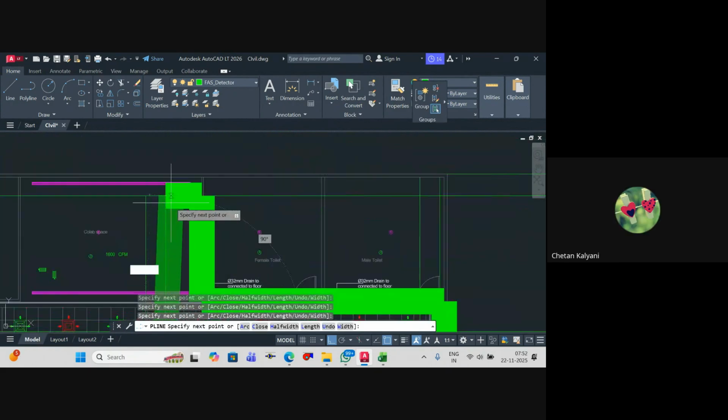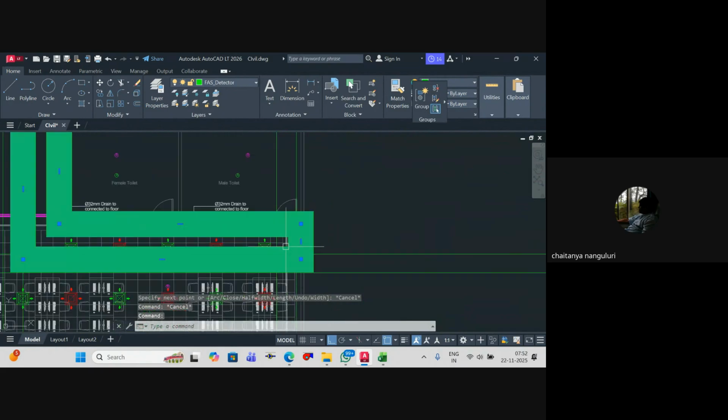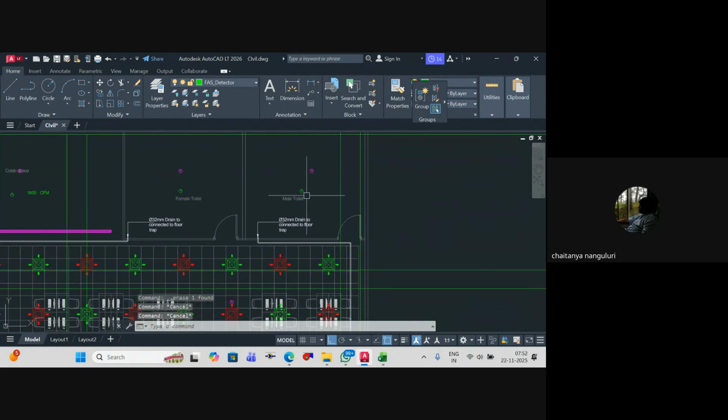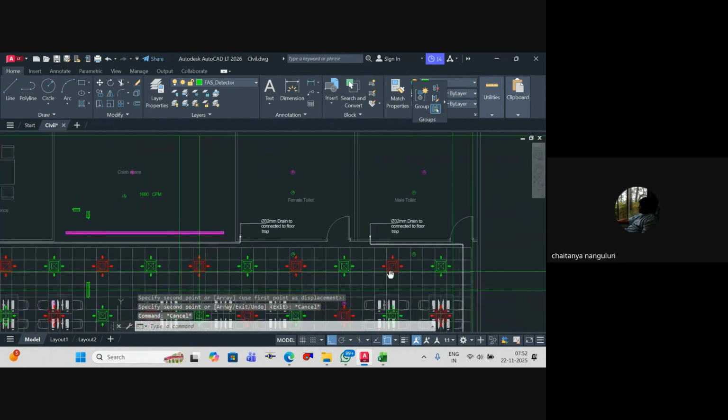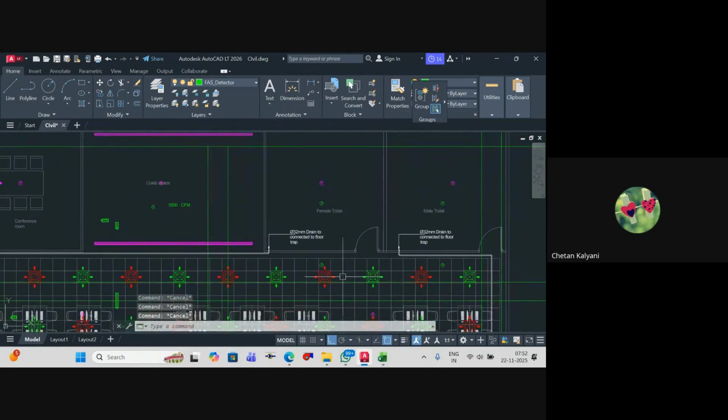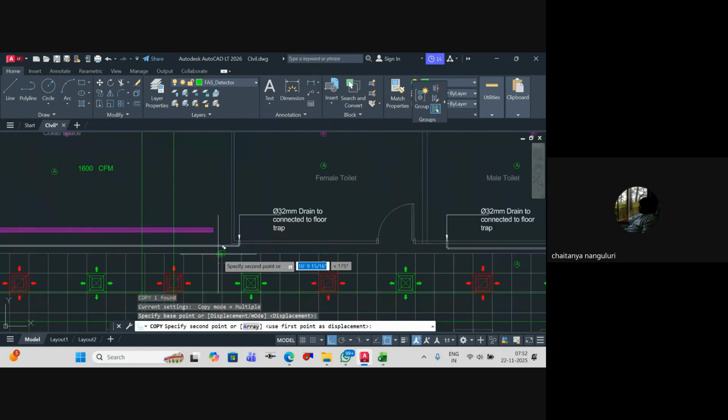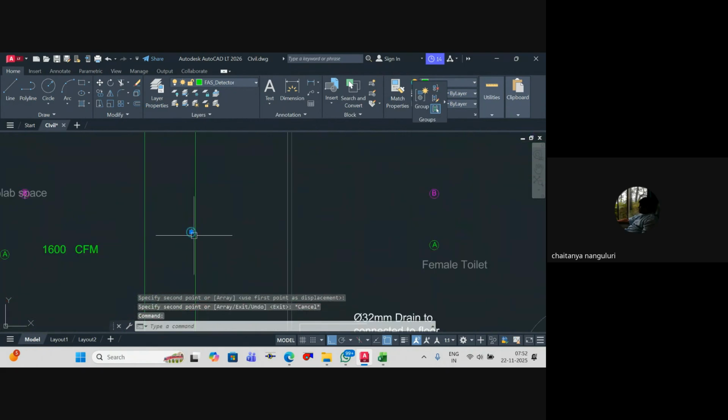Yes. Right. So this is a blind spot for the detector. So here I have to place one or two more detectors. One detector will be placed here, and two detectors if I place, it should be sufficient. Understood or not? Understood, sir. And here it might take a lot of time, so in this zone also I'll place one more at this location.